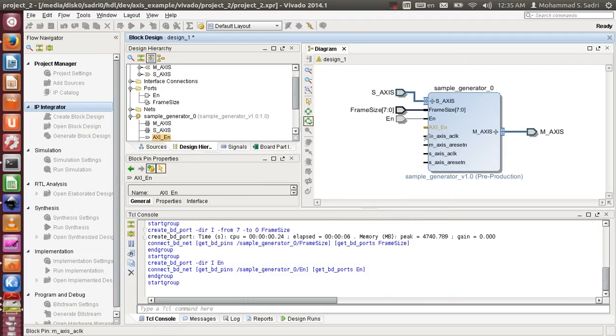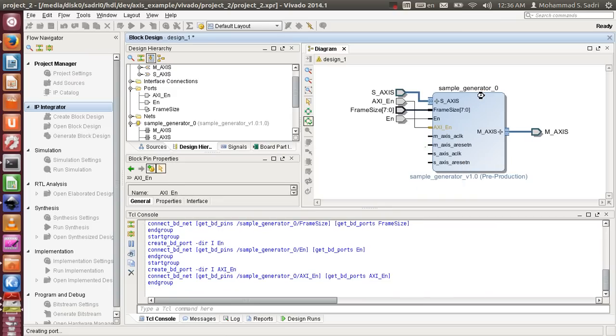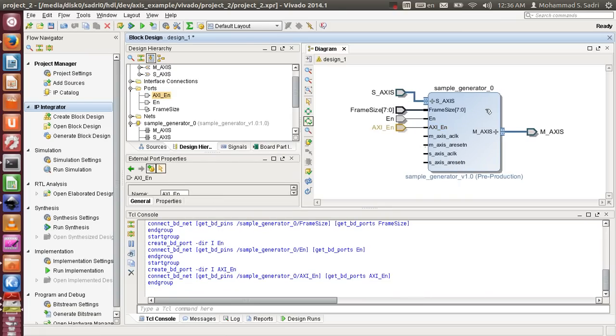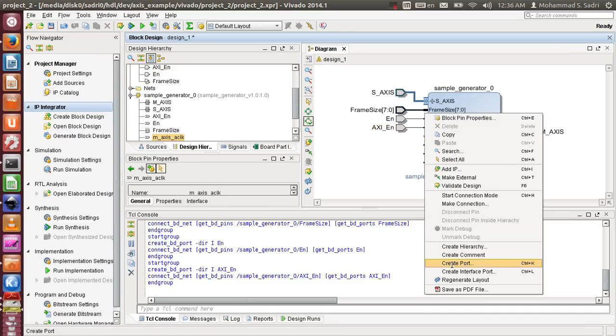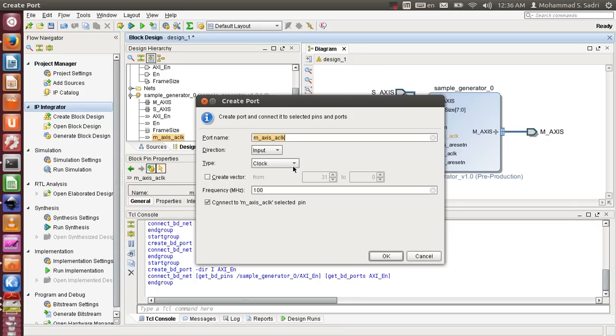And for now I connect these two clocks together and I connect these two resets together, and in practice it is the same. So for this module, as a kind of interface module, I don't have two clocks, I have just one clock and one reset. So I define this as a port, create port, and create port. We should wait. And this one is a clock port, and it has a kind of timing constraint on the port. So the port has also its timing constraint included, I would say.